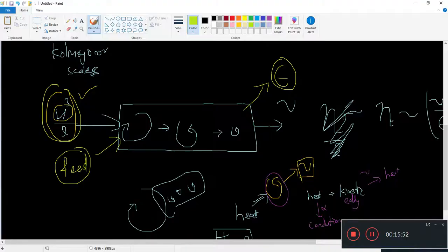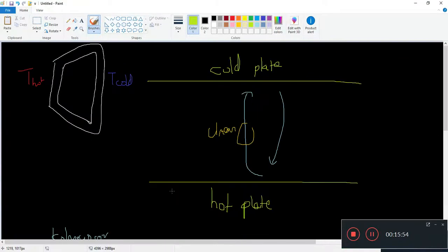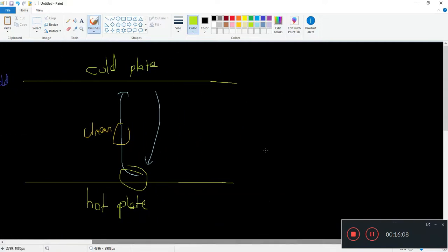Natural convection has to happen at the interface with the wall, because this is where most of it is happening. You have the steepest temperature gradients here, and so most of this natural convection occurs in the vicinity of the wall anyhow. For example, say you have a hot plate that's going to heat up some air.